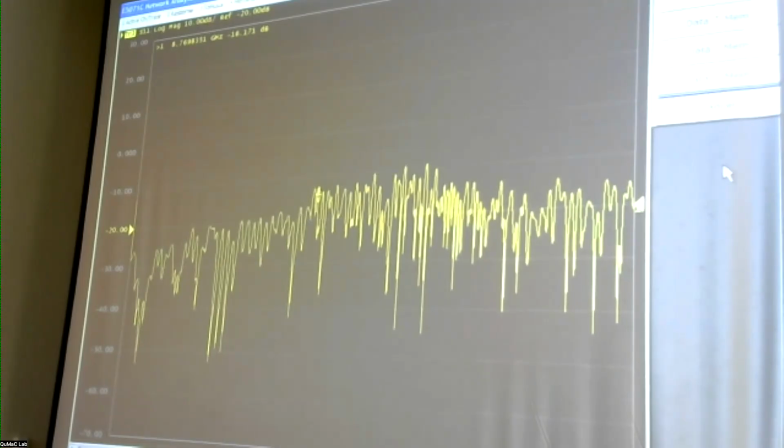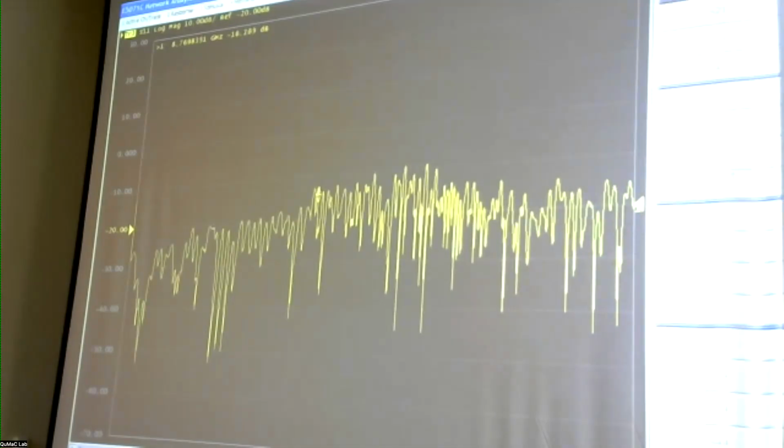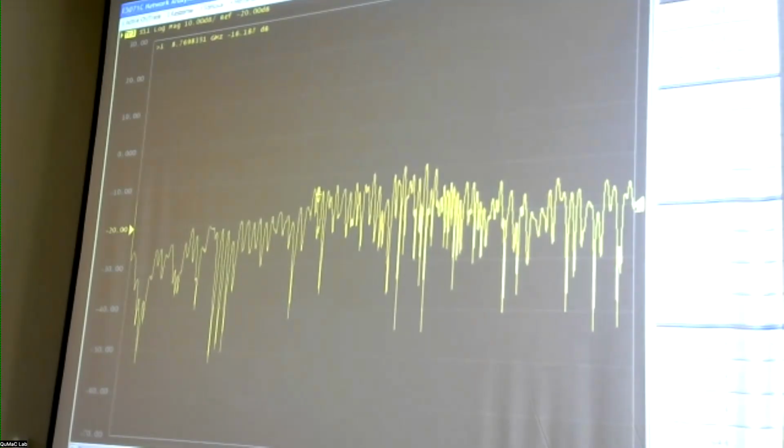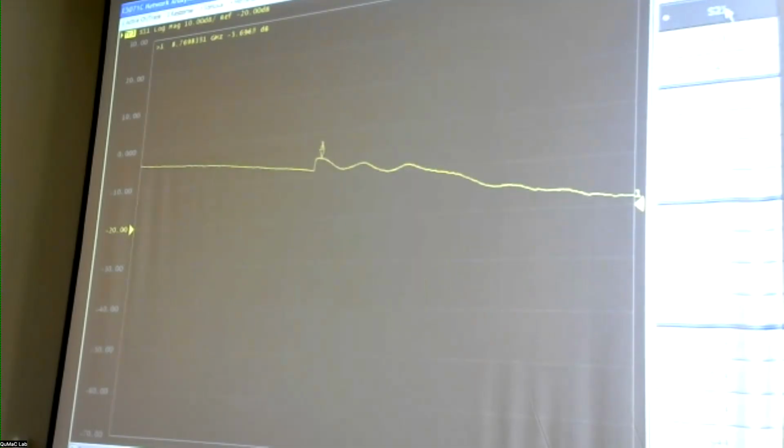But I don't want to, if this cable has some finite losses, I want to remove it from the analysis. So I just divide it by the reference space, which I have saved. So the way you do that is you go into this memory and you say data to memory, which means the current trace goes into the memory, and then you can do any operation. So this thing was set to data divided by memory, which is also why the S21 was looking too perfect.